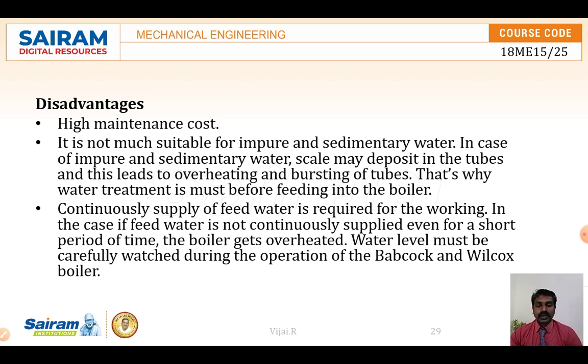What are the disadvantages of this Babcock and Wilcox? Here it is not suitable for impure sedimentary water. The water should be purified, so we need some purification process. Otherwise the sedimentary water gets sedimented, the salt gets sedimented inside the pipe. So a scale may deposit in the tubes, and in future it can damage the pipes.